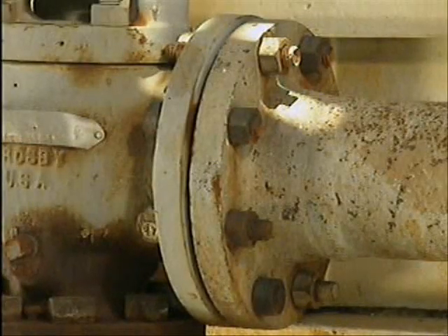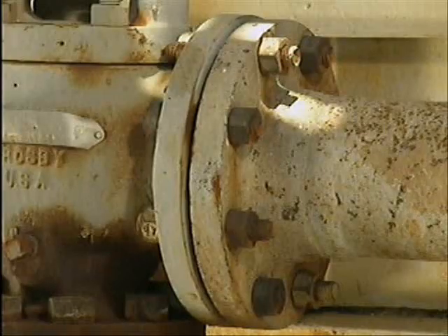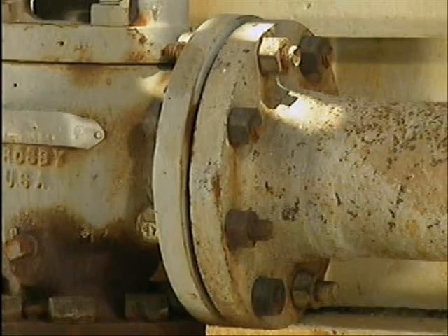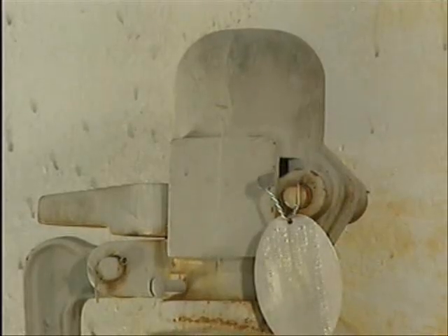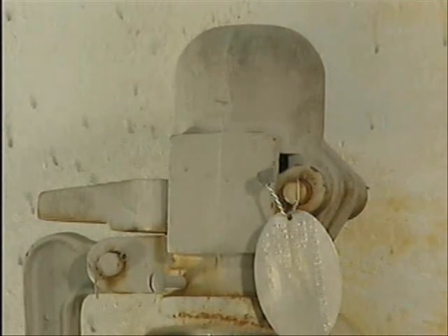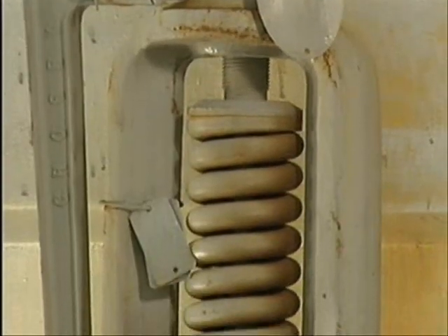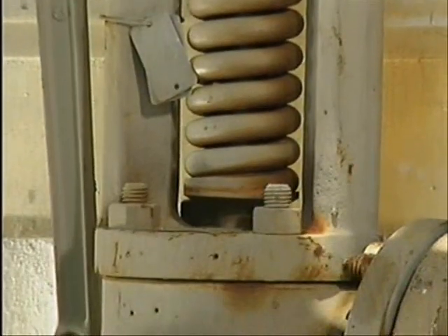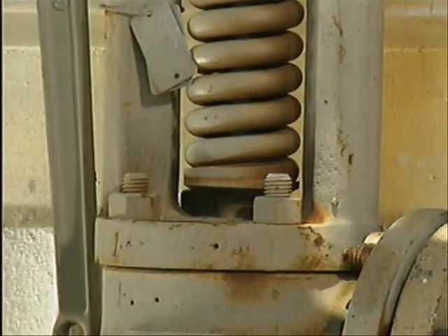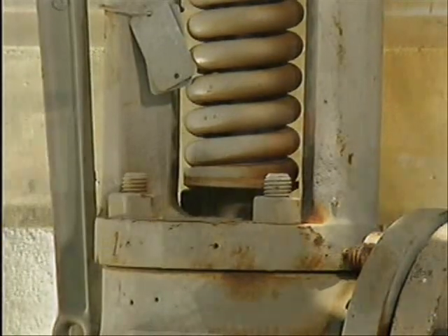Check for signs of leakage or leak-through at the discharge piping bolts and possibly around the yoke or bonnet bolts. Some valves have a yoke and a bonnet that are 2 connected pieces. Others, like this one, have a single piece that may be called either a yoke or a bonnet. For consistency, we'll use the term yoke.